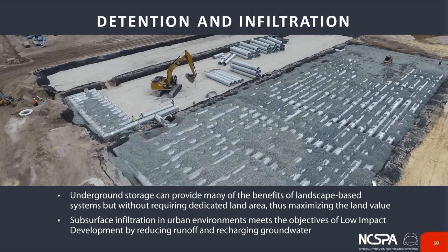So, why do we want to detain water? Most urban agencies have a requirement that the runoff created after a property is developed does not create any more runoff or impact to the local watershed than it did before it was developed.